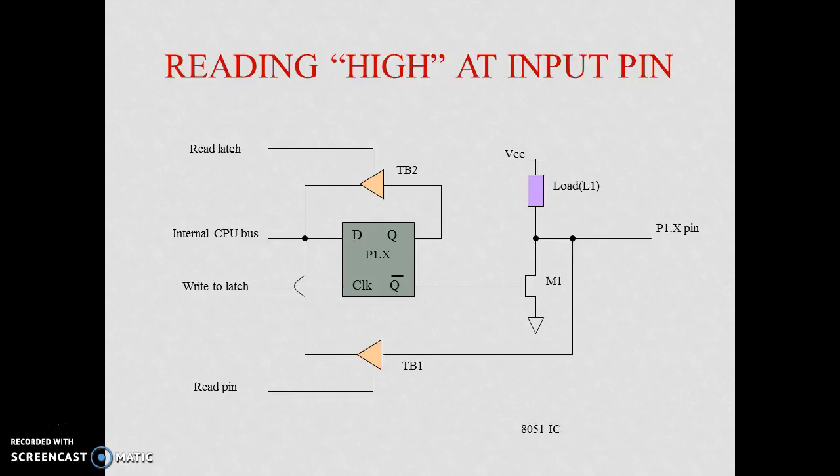Similarly, how do we read the port? Suppose I want to read a high at the pin input. How is this high read by the microcontroller? For this purpose we have to configure the pin with a command like MOV P1, #0FFH, so that it is an input port.